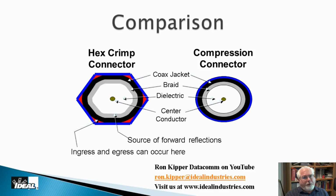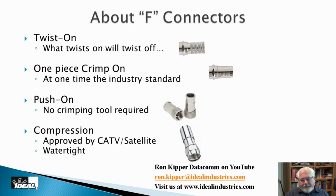And they like to use compression coax connectors, which is the one on the right. We'll use everything nice and sealed and round and watertight and all kind of good stuff. So that's the connector of choice, okay? Now, the next connector on that list is a push-on. And if I'm going to give the homeowner a toolless solution today, I'm probably going to give them one of these type of push-ons. And you strip the cable properly, and as the name implies, you just push it on and it stays on. And you can get them off, but it's a lot better than a twist-on, I'll put it that way.